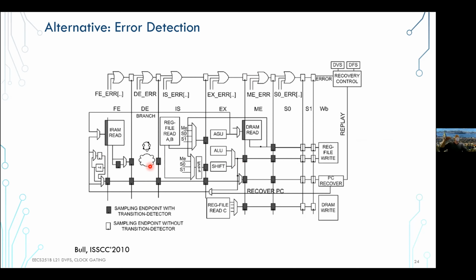And then I know what should be the right setting, right? Of course, that comes with additional overheads. First instruction replay if you're wrong, then also this additional checking logic, depending on whether you want to do it per stage, etc., or per whole unit, things like that. One thing though that it's good to keep in mind, we didn't really talk about it earlier, was even in the core DVFS loop, and this may be something for you to think about a little bit.